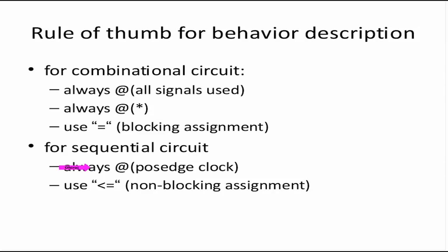Now latches are bad from a timing point of view. Hardware wise they are fine, area wise they are fine, but nobody likes them when it comes to timing checks. We'll see a few reasons why in the next unit. So it is very important to know right at the start if there are any latch problems in the design. How do we know that? We review the code. We see that the always blocks where we intend to implement combinational logic are properly defined. All the cases are defined.